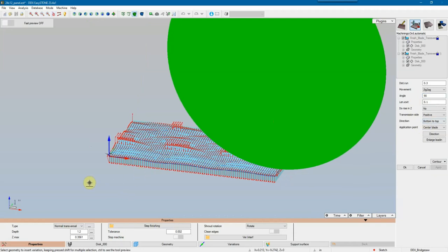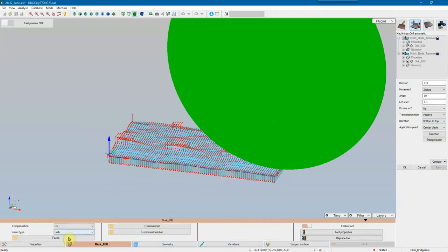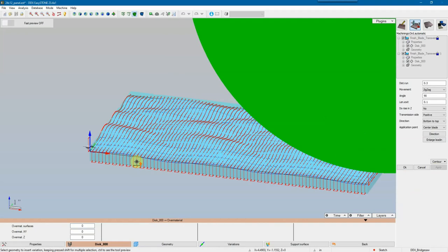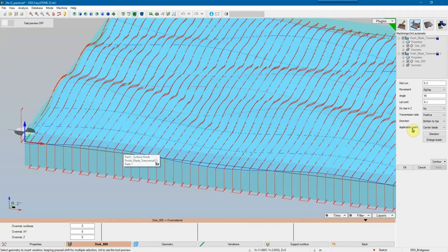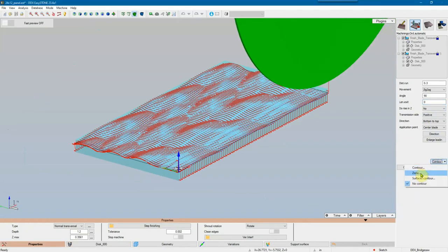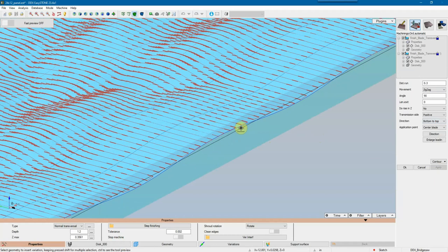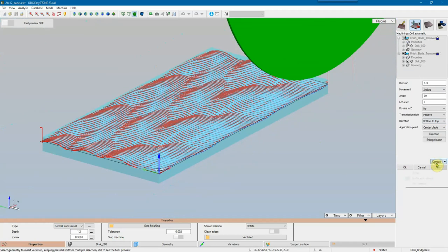I'm still coming out, but over material I want to get rid of for this operation. So I have this drop down on the edge of the surface. I do not want that, and I'm pretty sure it's because of this. So I can either make it 0 or just keep coming down with it. There, that'll do it. That'll keep that saw blade on that surface. I chose a contour, went by a surface contour, and now we're contained inside.